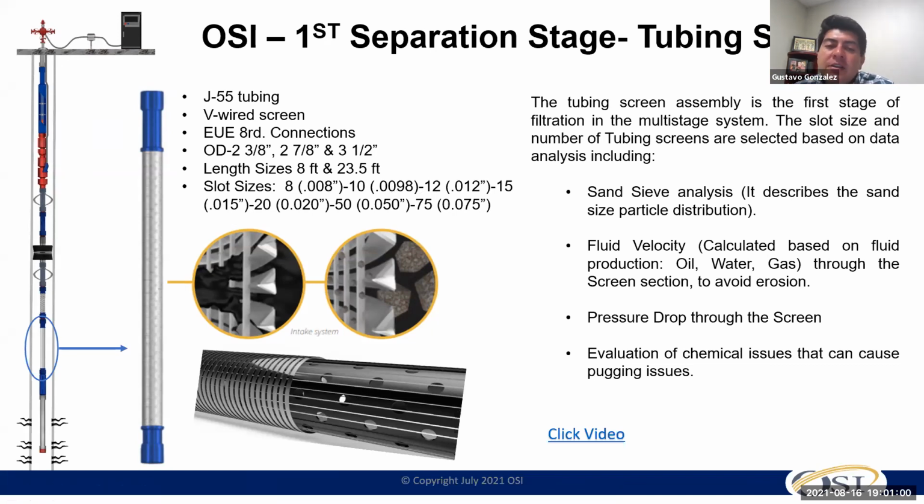I know your artificial lift system can lift the sand, but instead of giving just the 3 holes that we mentioned at the beginning that the ESP has as an intake, instead of having just 3 doors, we're going to give you 1,000 doors that you're able to open and regulate how much sand can actually access through.